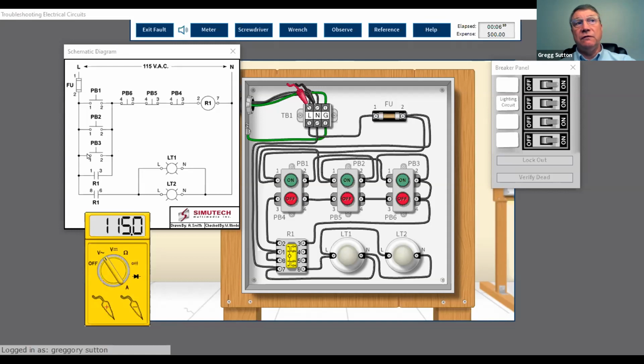Then after all those devices, it comes back into the enclosure, maybe here. So something that's very effective is starting at the beginning, which you just did, and then go right to the end. What is it we're turning on? Now, you might think it's the light bulbs here, right? But what are we really turning on with the push buttons? We're turning on the lights and the relay as well. Yeah, really the relay's got to be energized for anything to happen.